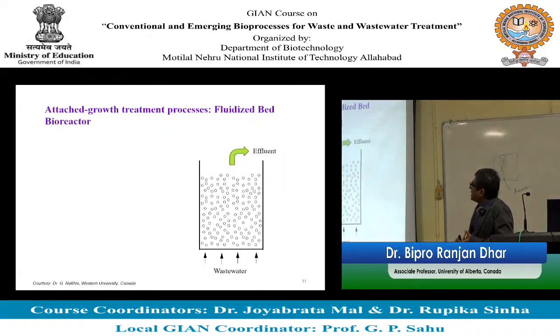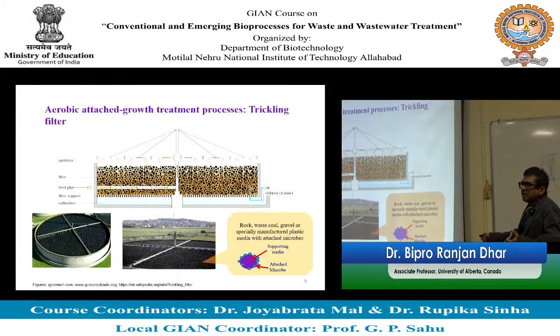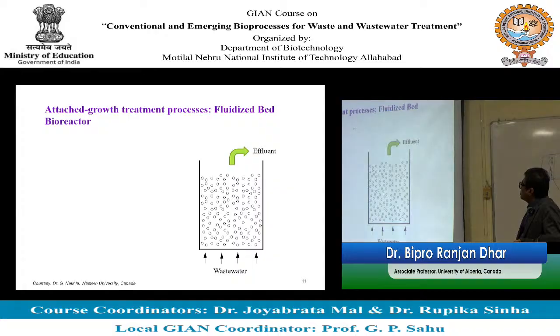So that is attached growth, but in this kind of filter system, or the trickling filter I was talking about, clogging might be an issue. To solve this kind of problem, other researchers found another design that could be more convenient, called the fluidized bed reactor. So what is a fluidized bed reactor? In a fluidized bed reactor, you have different types of inert media, which could be plastic or other biomaterial or any natural material.